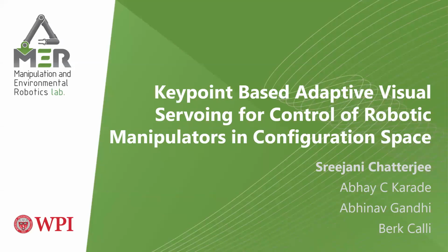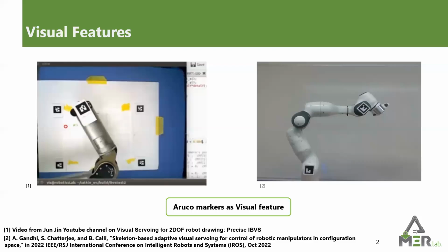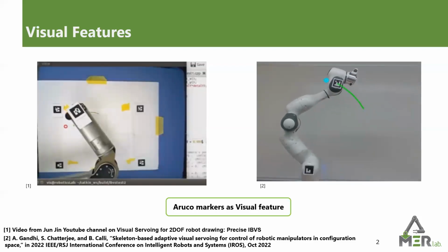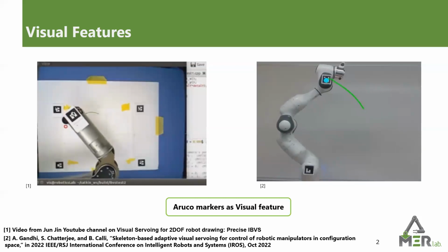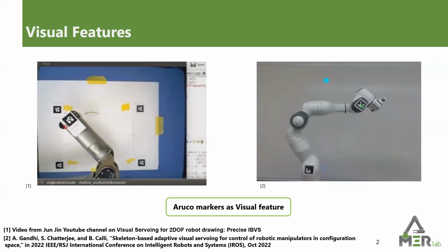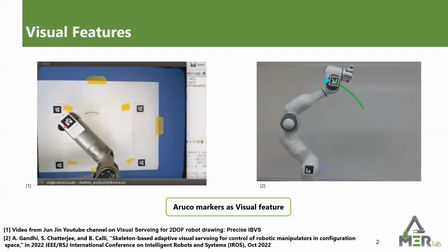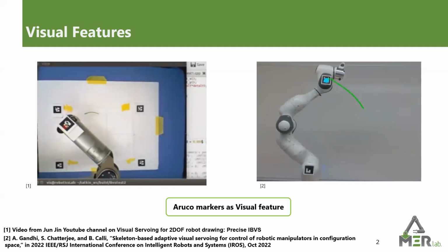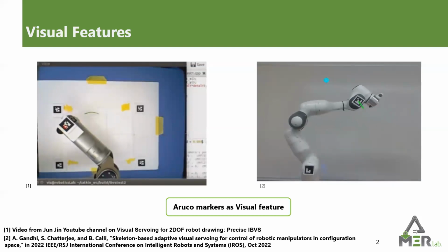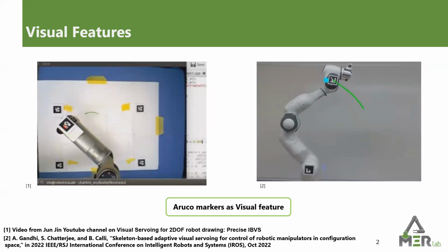This paper presents a novel keypoints-based method to control the configuration of a robotic manipulator in image space using an adaptive image-based visual servoing scheme. In existing literature, image-based visual servoing in an eye-to-hand setup controls the end effector in the image space using specialized markers like ArUco. These markers are largely dependent on the environment and could be unreliable during control experiments in unfavorable lighting conditions.